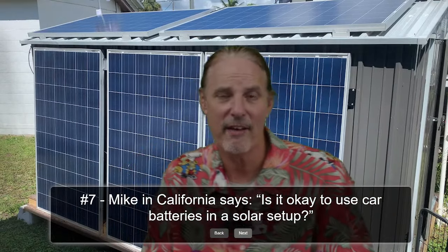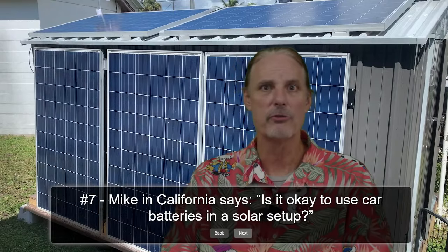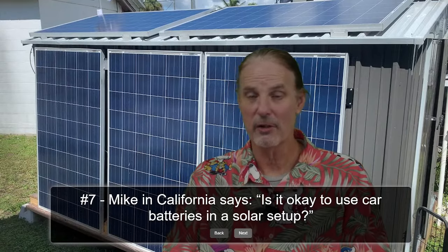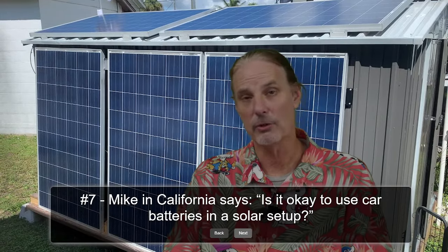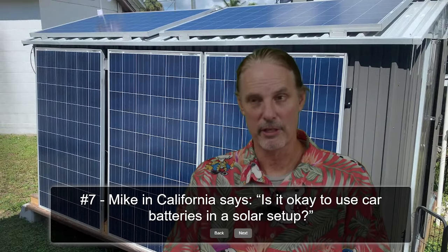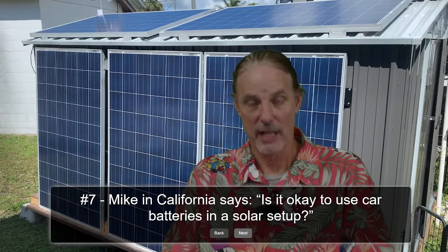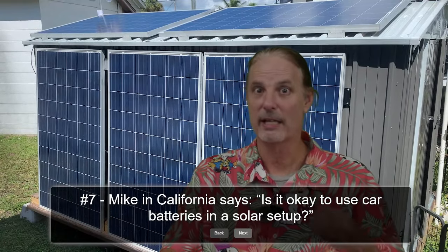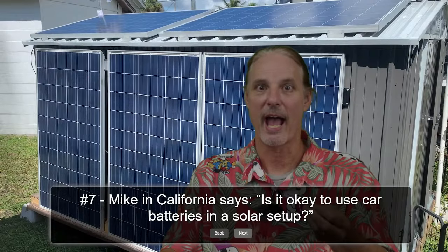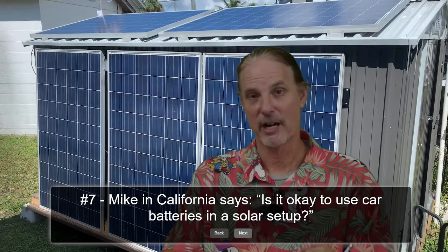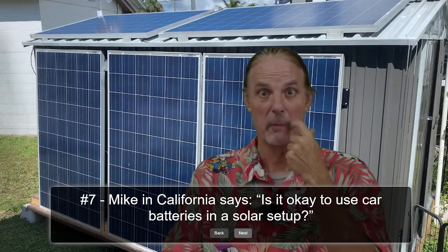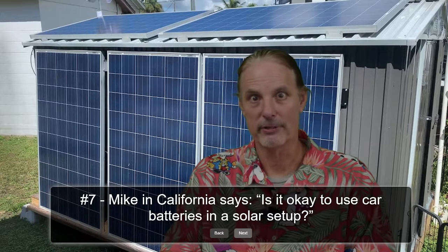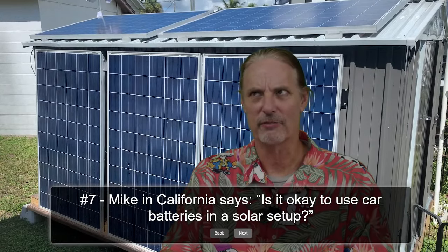That means that if you have a 100 amp hour 12 volt solar system running on lead acid, technically you only have 50 amp hour battery because you can't use it past 50%. If you have a lithium iron phosphate at 100 amp hours, technically you can use all of the power that's in that battery. The only thing you got to be careful about is the state of charge needs to be accurate. And calculating that from a lithium iron phosphate is much more difficult because you can't just use the battery voltage to really determine how much energy is left in your battery.